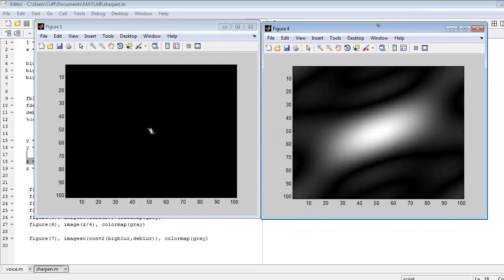Okay, you see that the blurring is happening more this way. So that is causing the frequencies in that direction to be removed. Not completely removed, but attenuated. Whereas the frequencies in this way, this is sort of a low-pass filter, but you pass through more frequencies in this direction because it's not blurred so much in that direction. So blurring is basically removing some of the high-frequency content of our image.